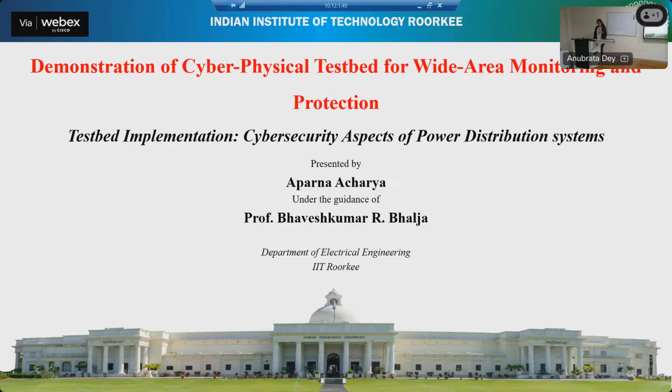As already explained, we can use multiple protocols. C37.118 is for synchrophasor, which has already been explained. While explaining the hardware, we said that the PMUs we are using are actually Axions, which have inbuilt RTAC properties. So we can use them for SCADA communication also, for example using DNP3, Modbus or IEC 104 based communication. I'll show one example in which we configure the same PMU's inbuilt RTAC to enable DNP3 based master and slave communication.